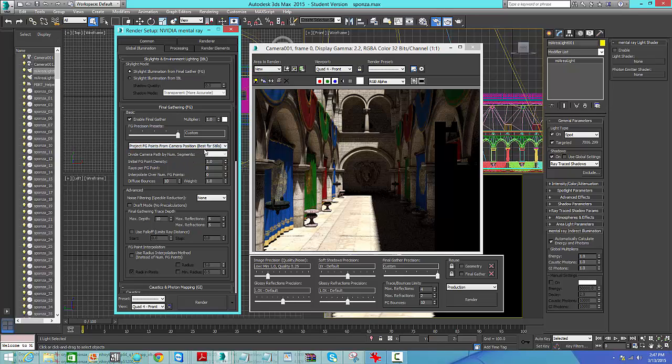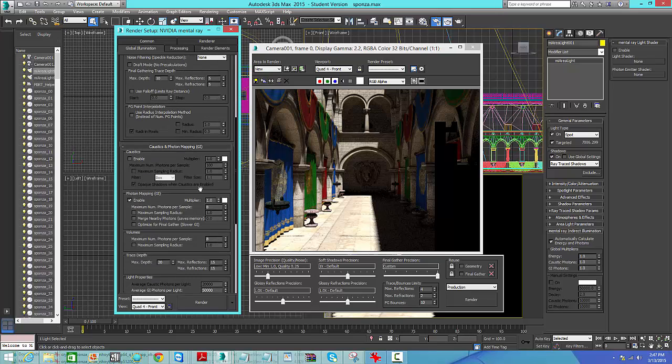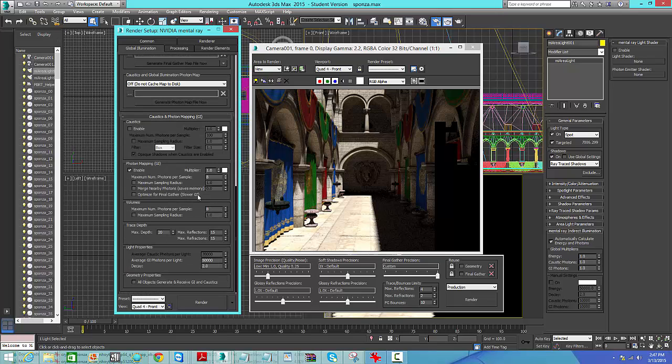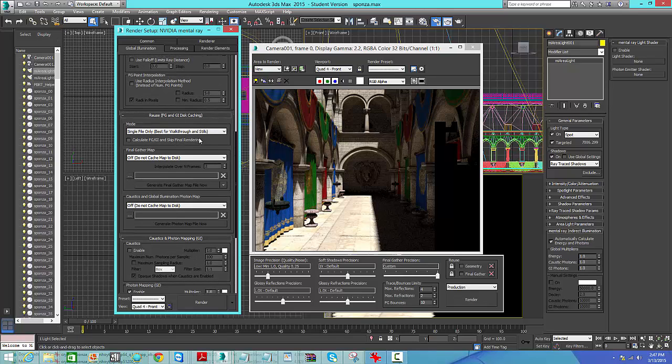Whereas this one works best for stills, as it says. But this can also be used for animation if you were to freeze the cache, like what I was talking about on this one down here. If you freeze the cache here, and you were to do an overscan render for that, then you would end up with a file that would be suitable for a small camera move.